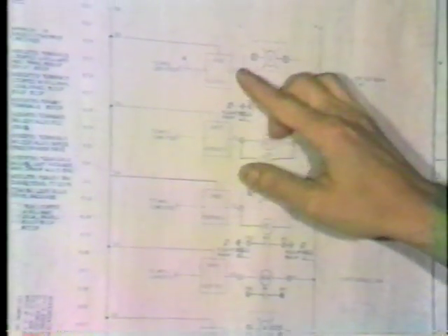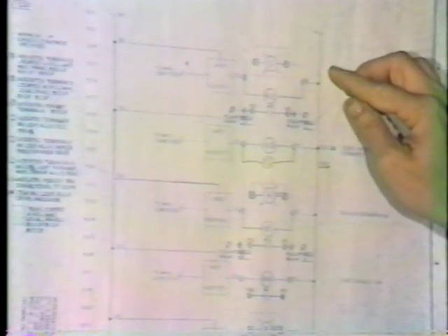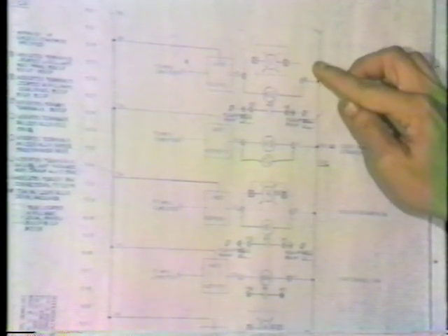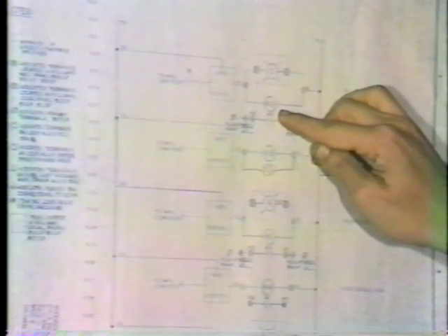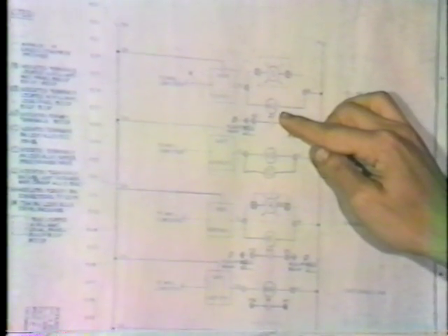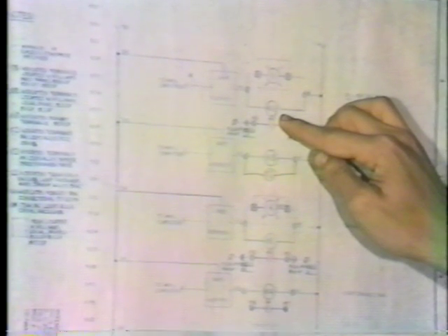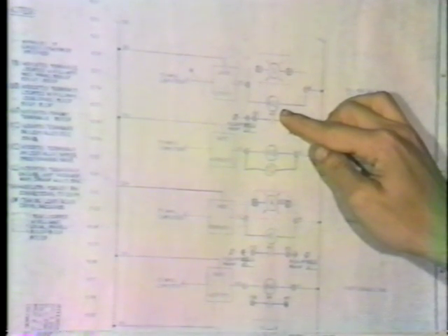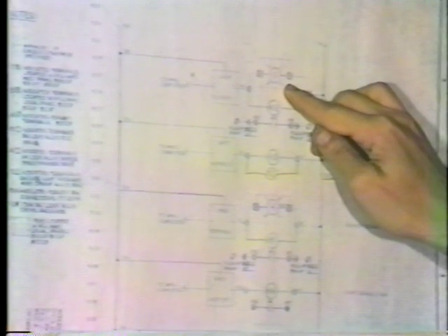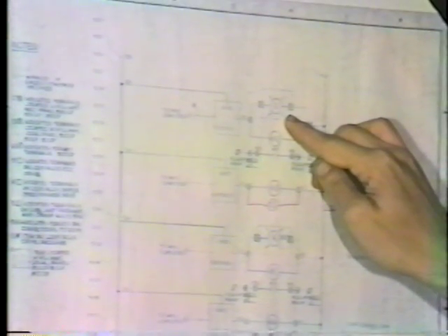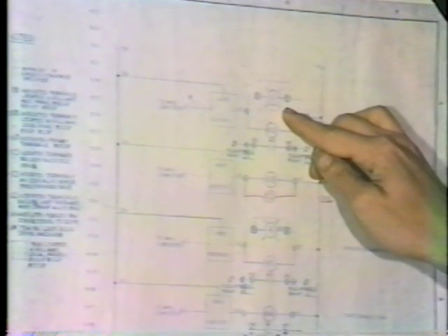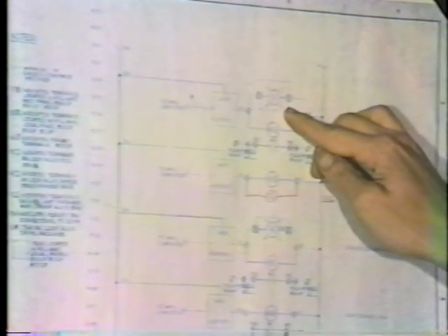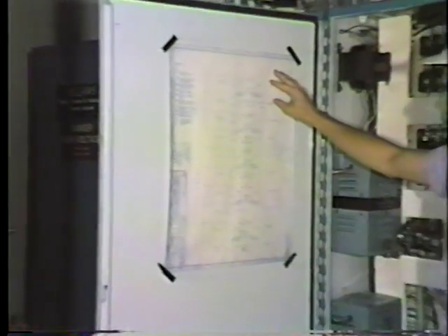Coming out of the output module, on some of the outputs we have indicators and/or relays, which fire the corresponding output to a motor starter and indicate with an indicator on the local panel. All of these then are your outputs. Would you please point to your outputs?